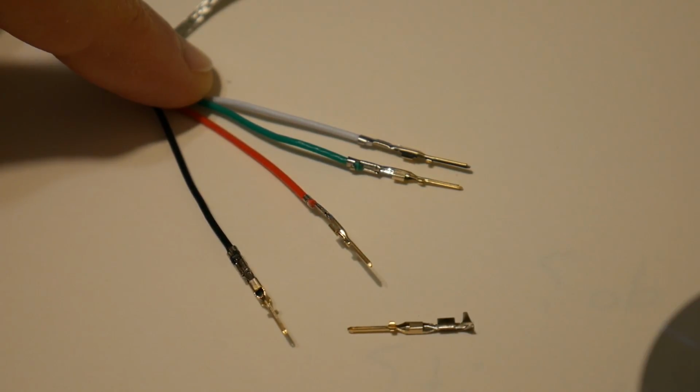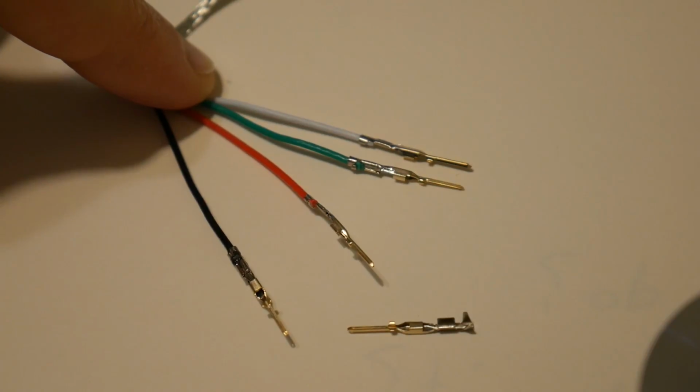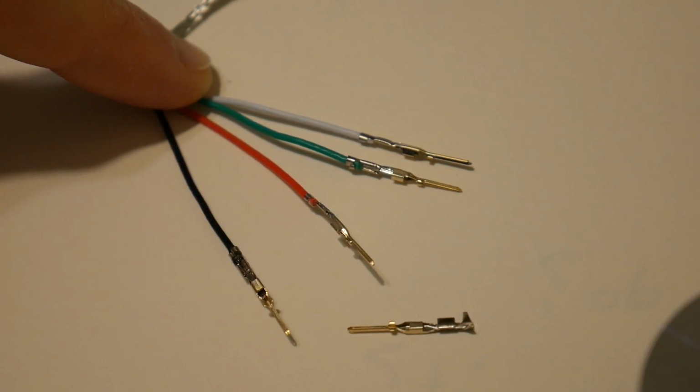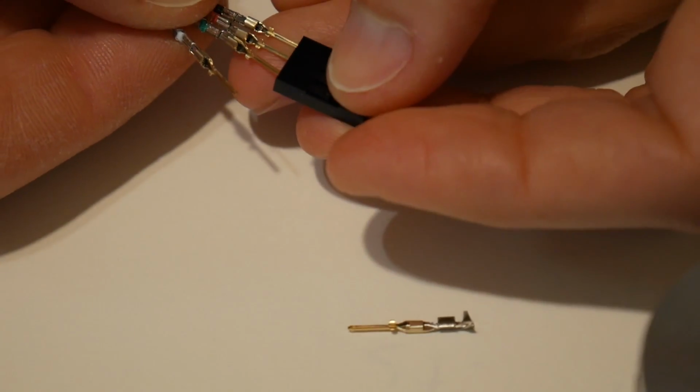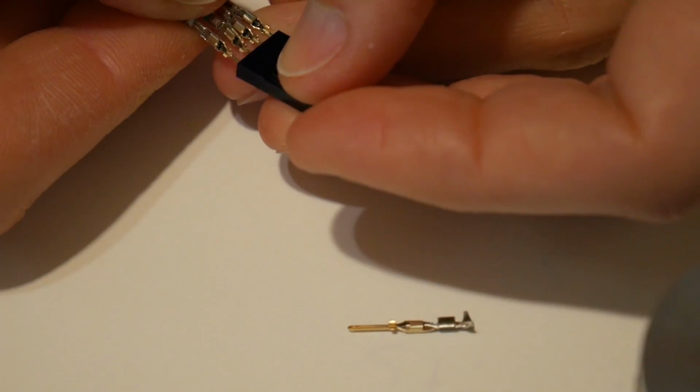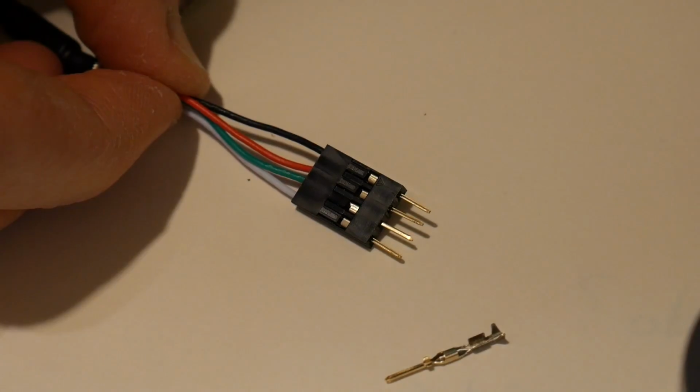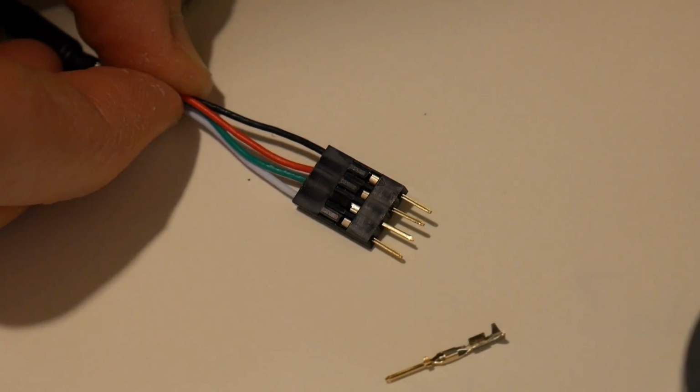The thing with crimp connections too is they're all closed up. They're inside the connection. It's very neat and tidy. Even if I soldered them, they have the risk of bumping into other things. So I'm going with the crimp connectors for now. Gives it a nice clean look and spaces them out so they sit on the header pins.